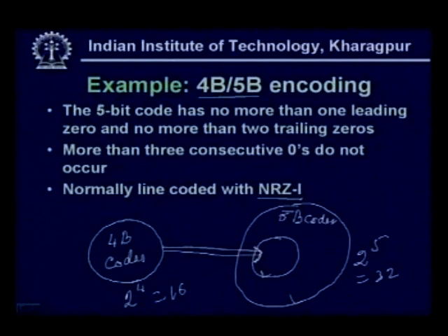You may be asking how error detection is done. So, you see, this is a code, this is also a code, but here it is a 5-bit code. Now, suppose after receiving at the receiving end, the code is not within this code set. So, it becomes a non-code. When it becomes a non-code, then we know that some error has occurred during transmission from the transmitter side to the receiver side. So, that is how error detection is possible in this case.